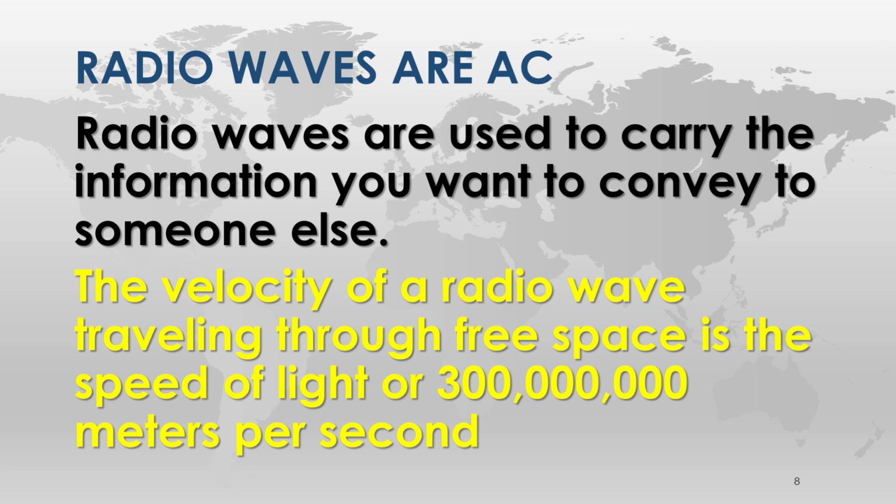It also has a relationship to how long your antenna is, because copper is a medium that is not a vacuum, right? So we convert 468, we'll get to it, but 468 for a half wave, or twice that for a full wave, gives you the actual length of the wire you need. And we always go with a half wave dipole, so it's 468 divided by the frequency in megahertz.